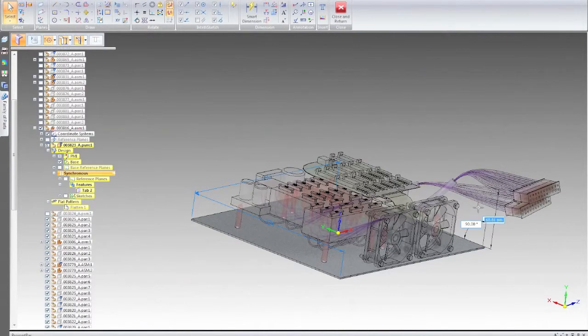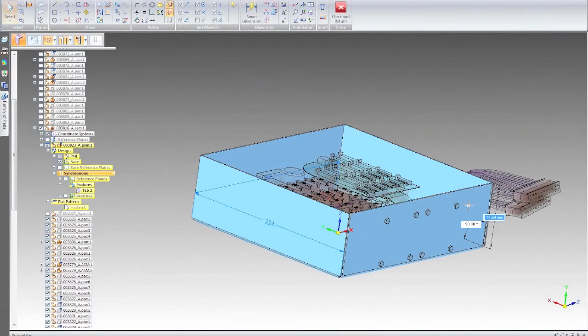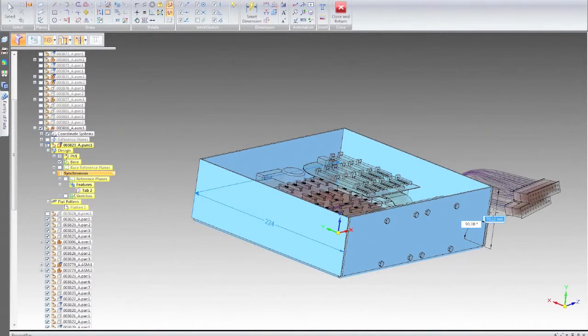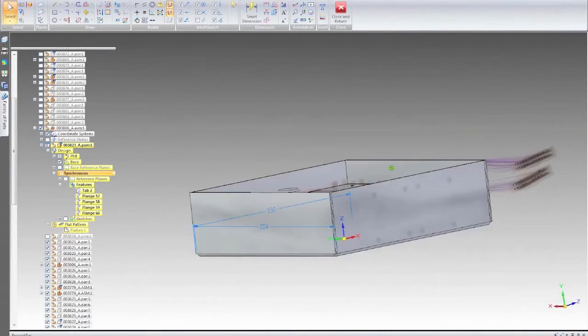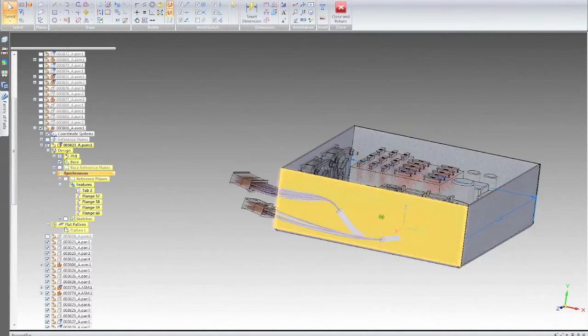All we have to do is, using Synchronous Technology, click on the arrow above and it automatically creates my bends, creates a contour flange, and creates my measuring point, and all I have to do now is input my distance on how high I want these to be. So we'll make those 70 millimeters tall. So now I have a box quickly and easily designed, minimal effort.